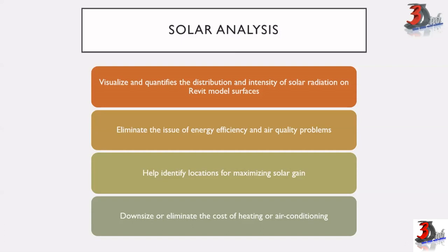Detailed geometry element types are not supported, including families such as generic model, group object, component, link object, and many others. The result for these geometry types will often lead to inaccurate results that are close to zero.